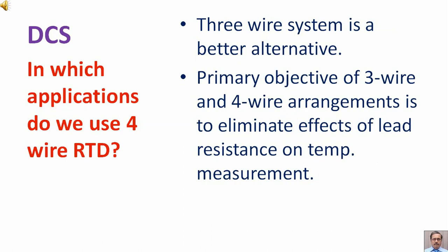Question: In which applications do we use a 4-wire RTD? Answer: A 3-wire system is a better alternative. The primary objective of 3-wire and 4-wire arrangements is to eliminate the effects of lead resistance on temperature measurement.